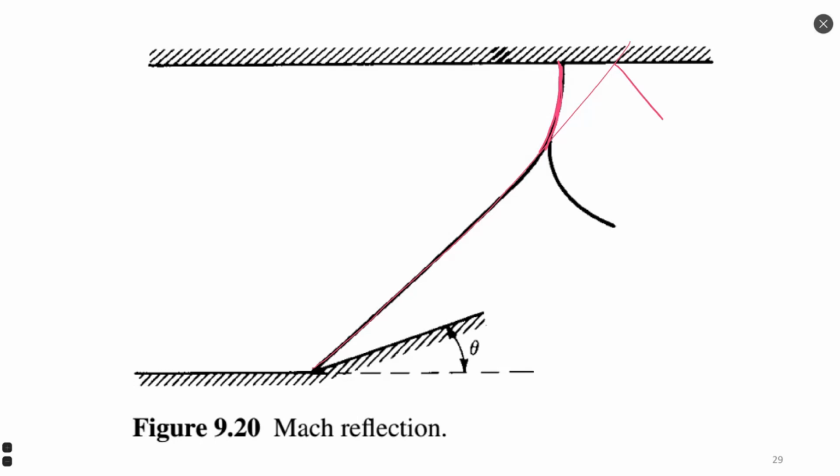This shape of reflected shock wave, which you can see here, can be seen in experiment and also can be seen in a numerical simulation. But unfortunately, such shape cannot be calculated analytically. But we already know how to predict analytically if such problem will appear or if there will be just reflection of oblique shock wave.